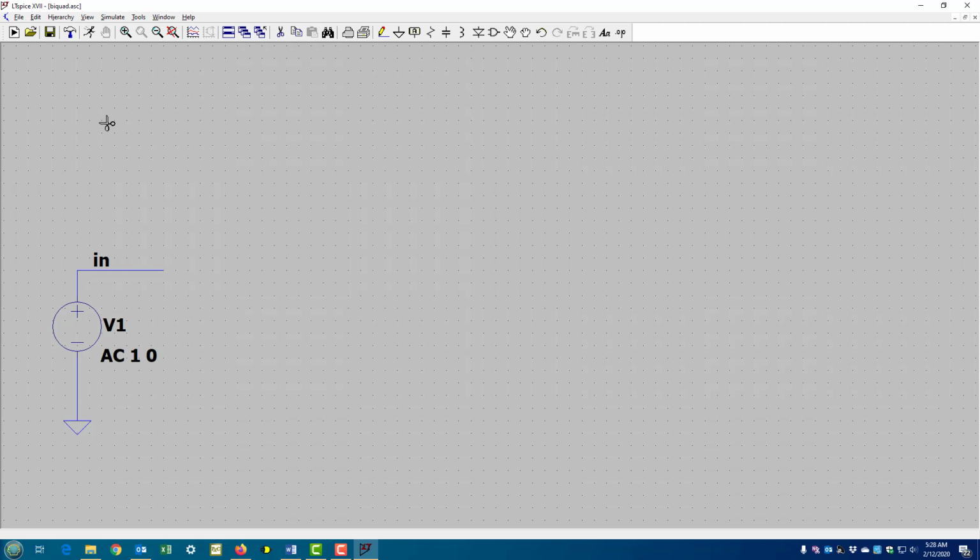waveform behind. So if you want to get rid of the cut, you can keep cutting. Cut is still active right now. Right click and it goes away. Now we're in the entry mode in LTspice. We're always going to use this kind of a source. This is just a phasor source, amplitude 1, phase 0, right? So this will sweep frequencies for our AC analysis. Okay, so we can just start from this element, and just go on and